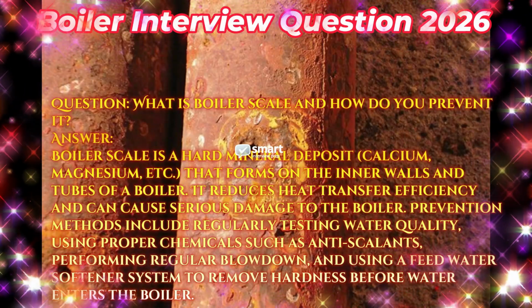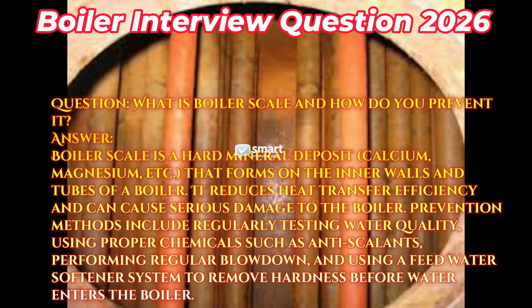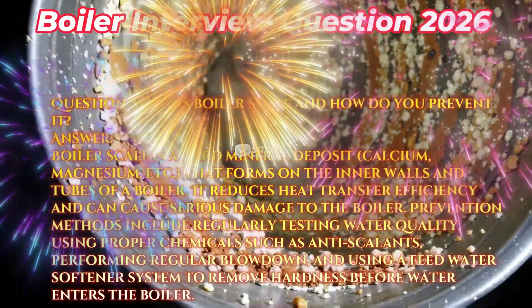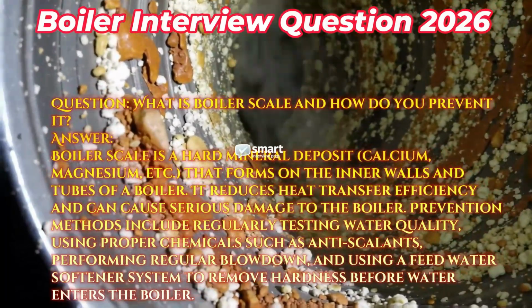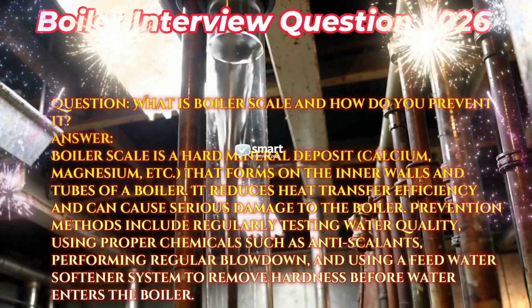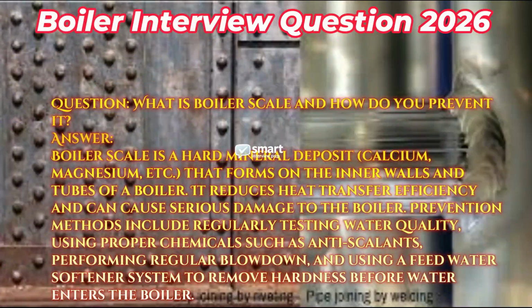Question: What is boiler scale and how do you prevent it? Answer: Boiler scale is a hard mineral deposit, calcium, magnesium, etc., that forms on the inner walls and tubes of a boiler. It reduces heat transfer efficiency and can cause serious damage to the boiler. Prevention methods include regularly testing water quality, using proper chemicals such as anti-scalants, performing regular blowdown, and using a feed water softener system to remove hardness before water enters the boiler.